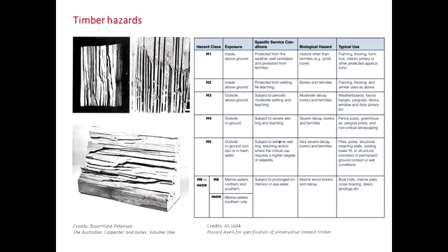There are also a lot of other hazards depending on the environment in which the timber is in, and also the sort of application. They are classified using those labels, H1, H2. Like for instance, H3 is what you need for decks. So let's say now that you are in a stage between the footing systems and the building frame. So let's pretend you have a deck in your house. You would consider the treatment procedures that you would do for an H3 class.